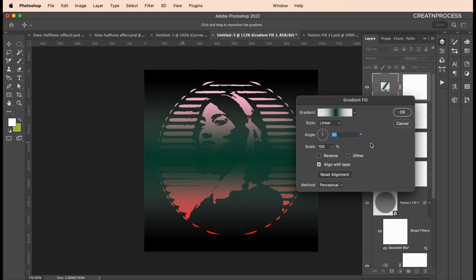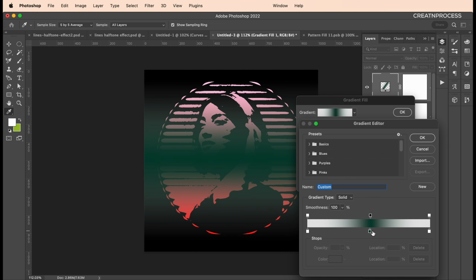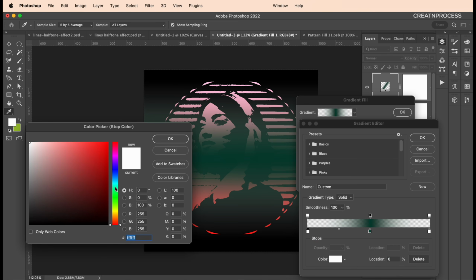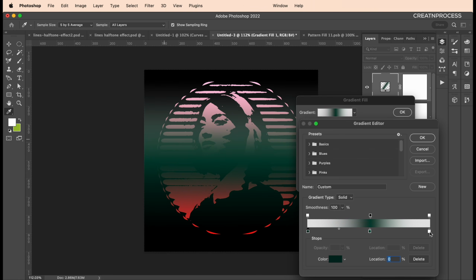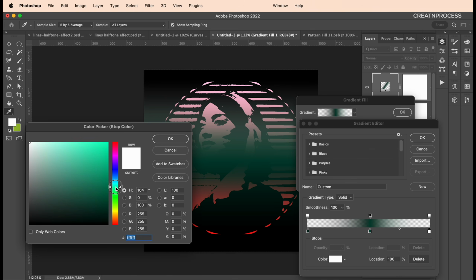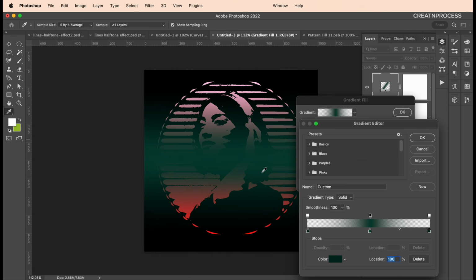I'm setting the opacity 0%. So over here this one is opacity 100, these two corners are 0% opacity, and I'm setting the colors to this dark color, dark greenish tone color for all the sides. Double click, go there, dark green, and let's do the adjustments.